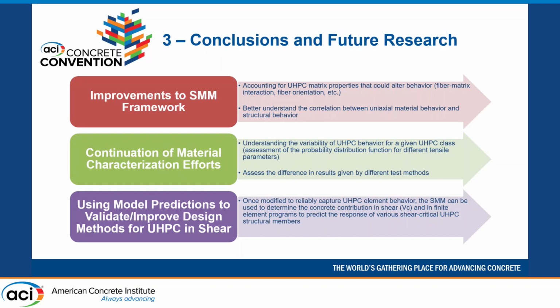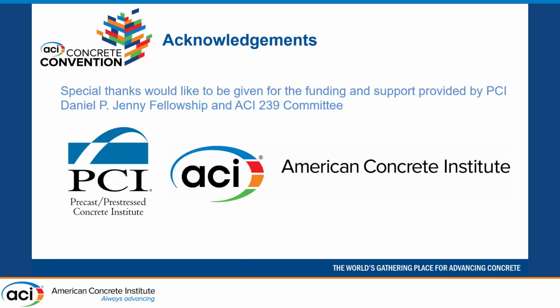And then finally, the predictions from this model, once validated, can be used to assess the concrete contribution in resisting shear in various structural members. So you can predict your Vc component in your shear design equations, and it can also be used in a finite element framework to predict the shear response of structures with UHPC elements.